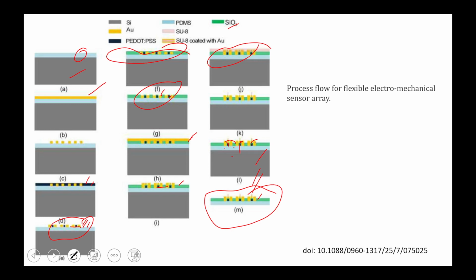Which technique is followed to fabricate the sensors in this method? Actually, I use a silicon wafer, with the silicon tool. Yes, same as what is on the screen. And then I deposit some semiconductor materials through CVD or RF sputtering, whatever the facility you have used for that fabrication.